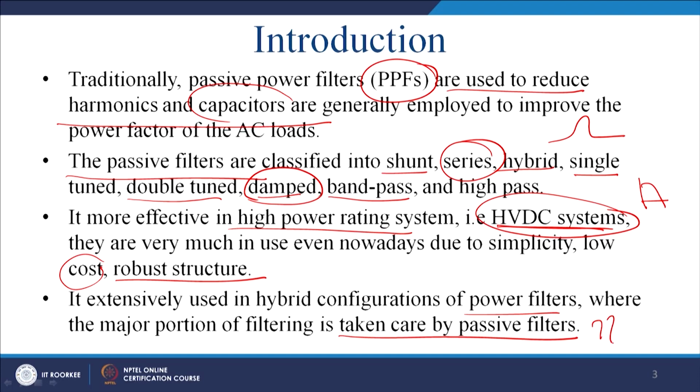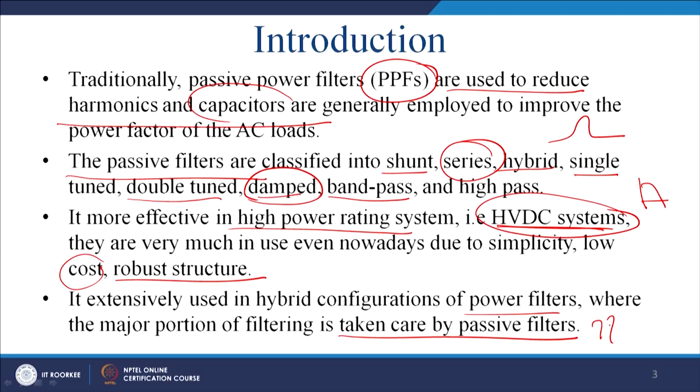but these statements now need to be validated, because with time the cost of these IGBTs is decreasing. It had a high patent cost, and unfortunately for this reason the manufacturing and all those issues came into the picture. Now, more than 30 years have passed since the IGBT came, so the price has been decreasing every year. And once you are putting in a passive filter, there is the cost of the inductor and the capacitor. Inductor comes with copper and iron.